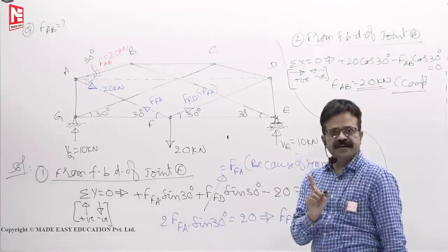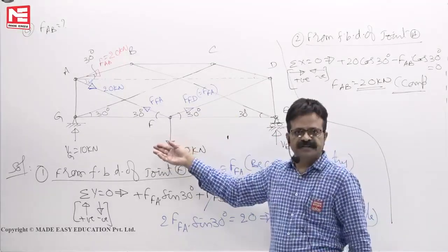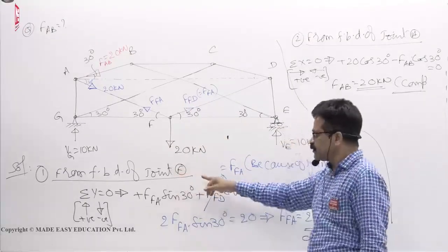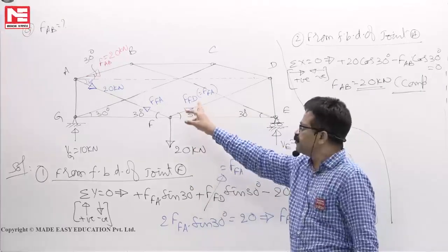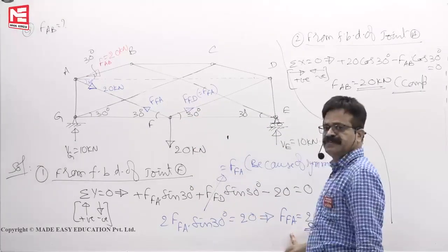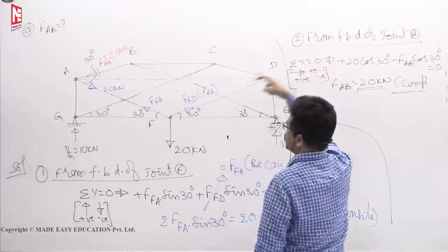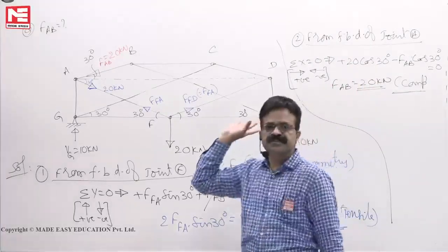So, in 2 minutes time, our task is to observe, can we use method of sections or not? Method of joints, if I have to use, which joint is better? Then, having understood that point, joint F we have to take first. Because of symmetry, they have to be same, and FFA we have to find. Once FFA is known to us, FAB by inspection you can find, this not required. In 2 minutes time you must do this much.